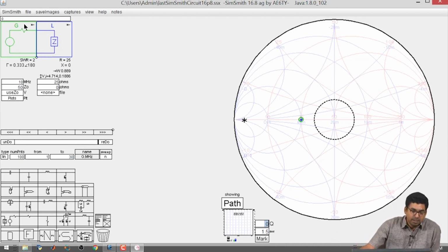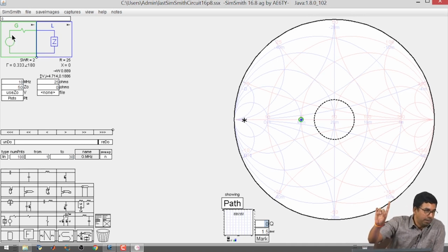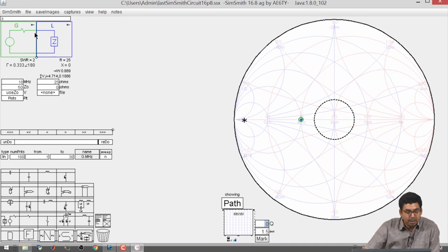Let us also remember that conventional transmission line cables come in predefined characteristic impedances. It could be either 50 ohms or 75 ohms. So, your generators are made in such a way that the termination is 50 ohms. Now, when somebody says that this generator is going to generate, say, 1 watt of power, the meaning is that at this end, if you match the impedance of 50 ohms, you are going to get 1 watt of power dissipated on the load.